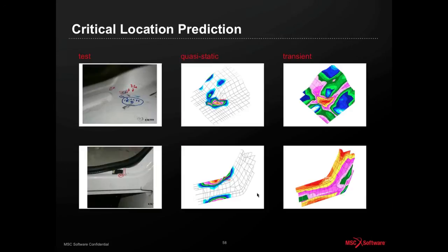And here we have not only the finite element-based results, but also some indication of what happens experimentally when this was tested, which is very nice. So we have lots of these results. What's interesting is how nowadays there isn't very much argument about the validity of these finite element-based approaches for doing fatigue and durability calculations. Here we can see that they are very good at calculating locations of damage. I think it's fair to say they're less good at calculating the absolute number of a failure.